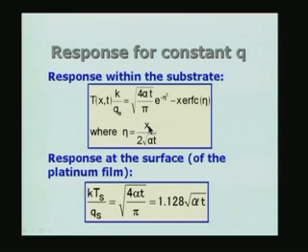X is the distance, t is the time, alpha is the thermal diffusivity, minus x times the complementary error function of eta. The student need not worry about the error function and so on. These functions are all given in the form of tables in handbooks of mathematics. So, we can just take it from there, and for the present, we will simply assume that the solution is obtained by a suitable method of solving the one dimensional heat equation.